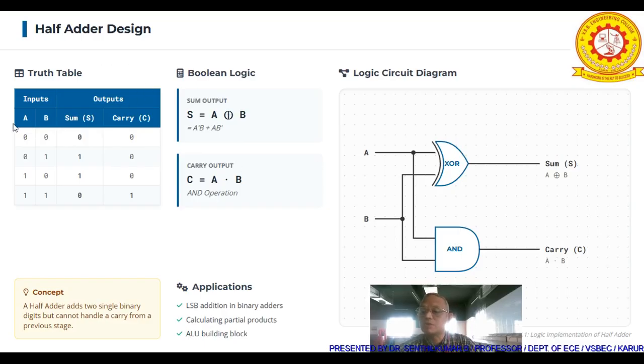So this is the procedure, as we saw in the last slide. First, you have to identify the number of inputs and outputs. Then list out all the possible input combinations. Then specify the corresponding required output. Based on that, by applying Boolean algebra logic, you can derive the function in SOP or POS format. This is the function in the form of SOP, sum of products. Accordingly, finally you can have a logic diagram like this also.